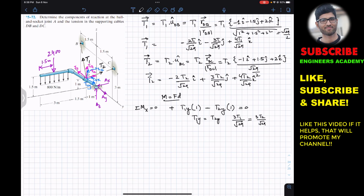So now this will cancel out, and we will be left with T1 equals T2 equals T. This means that the tension in both the cables is the same. And as we can see, this whole assembly is symmetrical about the YZ plane, and the distances of point C and point D from the Z axis, or from the XY plane, are symmetrical. So that is why T1 is equal to T2, equal to T.